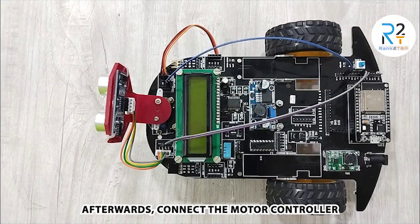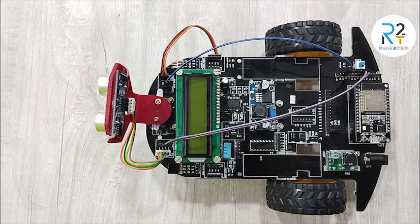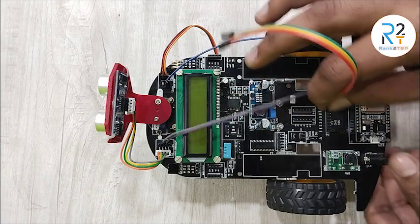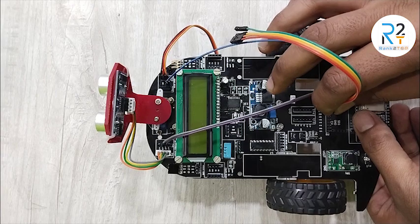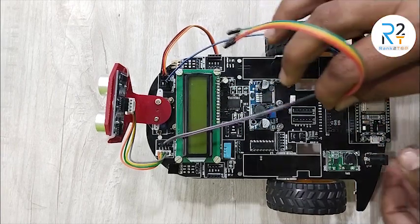Afterwards, connect the motor controller pins to our ESP32, D27 to D33. These 4 pins connect with IN1, IN2, IN3, IN4.